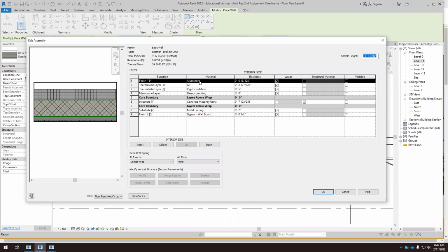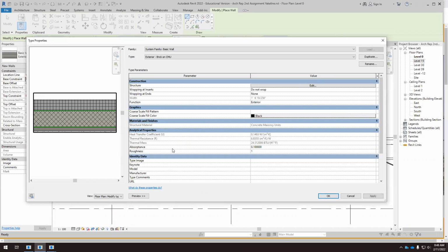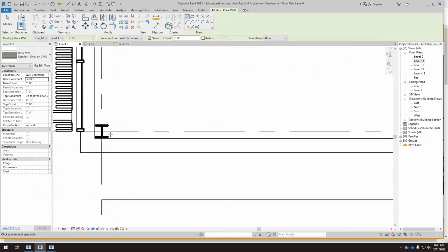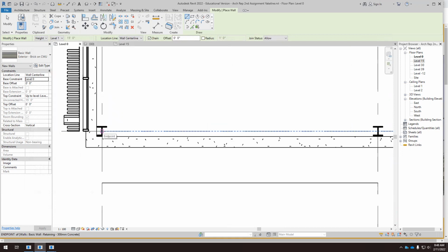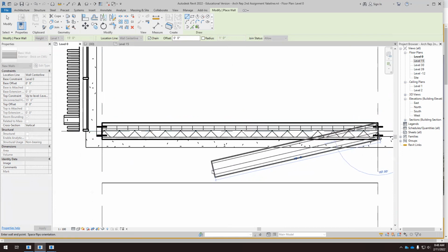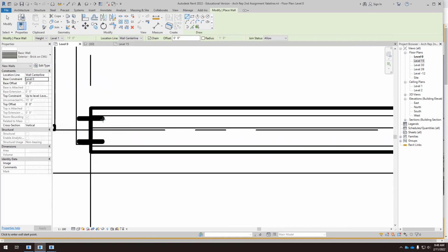But this is important now, and it's about placing the wall in the right position. Okay. So I'm going to place the wall here. Again, don't do it a continuous wall because we have this and we are going to analyze this. So we have to interrupt the wall here. Okay, so as you can see, this is not acceptable.